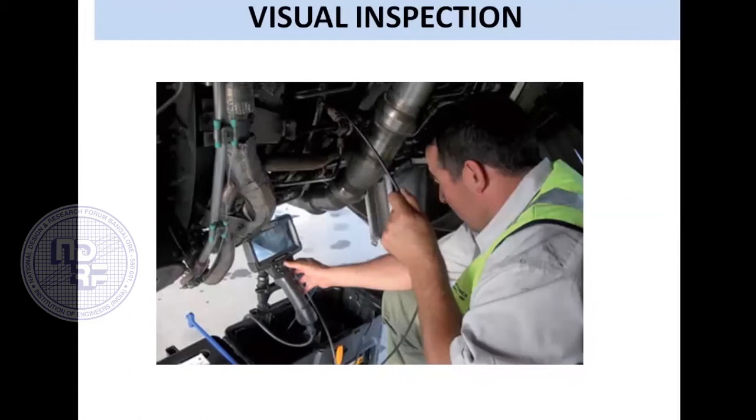This is one of the fundamental ways of checking whether the aircraft is serviceable or not, or if there are any defects. So after every aircraft goes for any flight, or comes back after any flight, this visual inspection is mandatorily carried out to ensure the aircraft structure is still holding good.